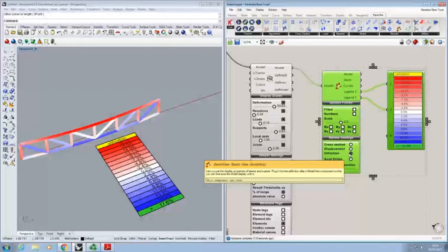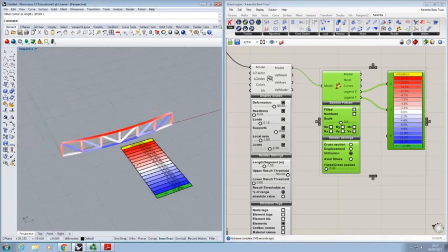So one thing to bear in mind with this utilization here is the fact that this utilization is only based on this cross-sectional stress divided by the capacity. So it doesn't check buckling. It could be misleading. And for slender elements, it obviously is not conservative and not safe.